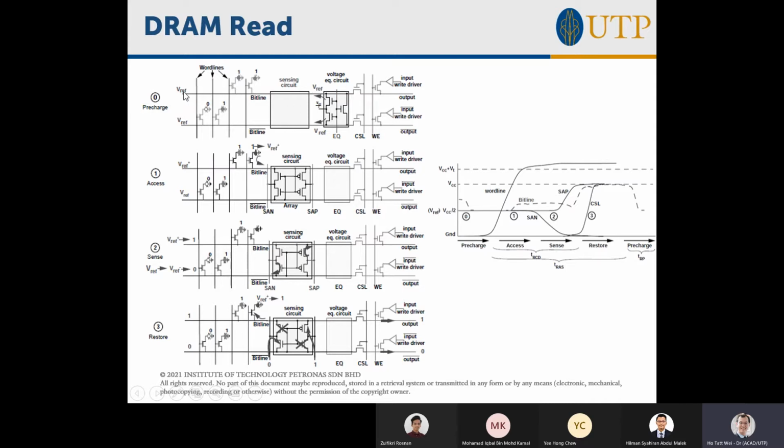I want to get your attention that this bit line is actually your data, so you are sending it out to the output. Here you see this is the bidirectional driver, right? You're either sending it out or you're receiving data in here. So if you turn on this transistor, there's a logic 1 on this line, the data will be read here. That means you have to make sure that at the output, there's nothing here. If you turn this off, the data can be sent out.